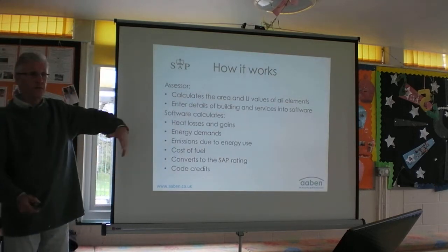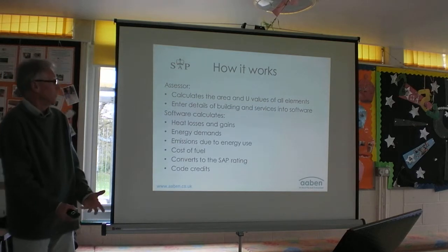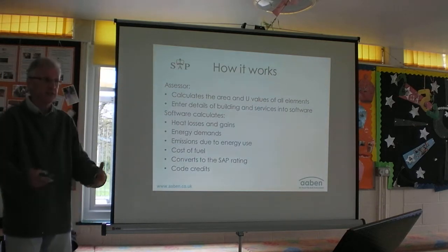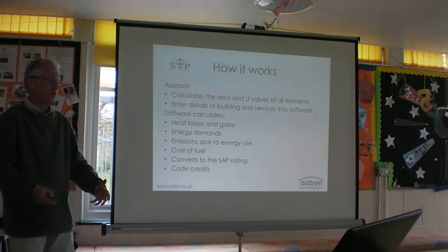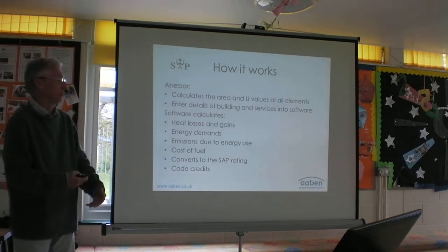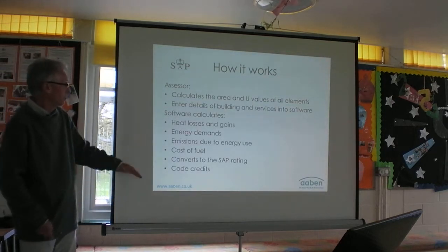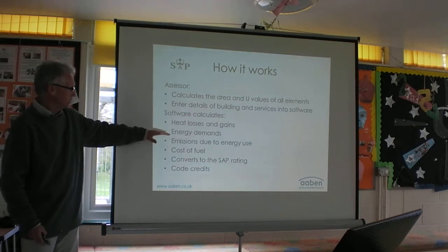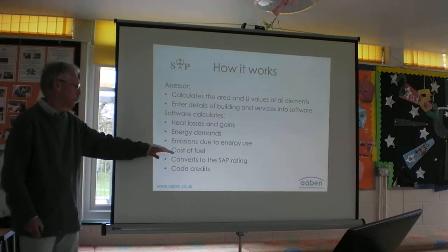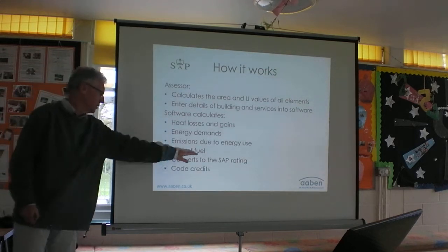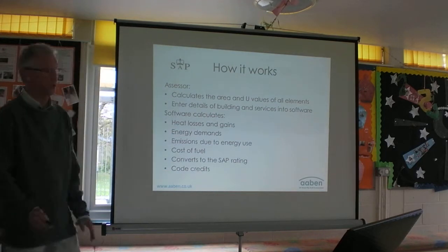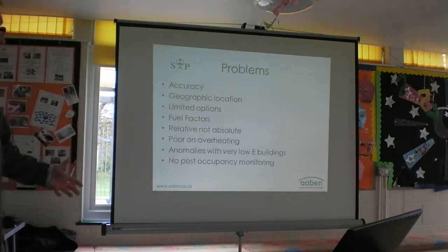Anyway, how it works? It calculates the area. We calculate how big the house is. We enter that in. We put in all the services and everything in, and then the software grinds through this huge calculation, huge sort of sum. Works out heat losses and gains, works out the energy demands, works out the emissions, works out the cost of the fuel, converts that to a SAP rating, and then it also gives us code credits. So that's just what SAP does.